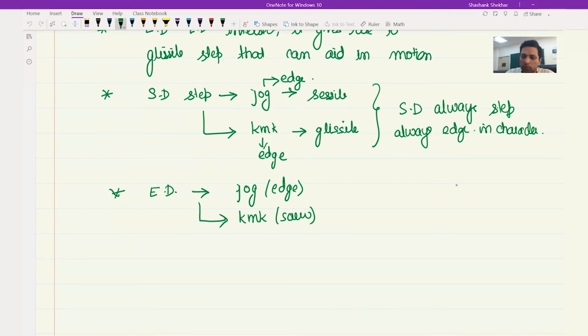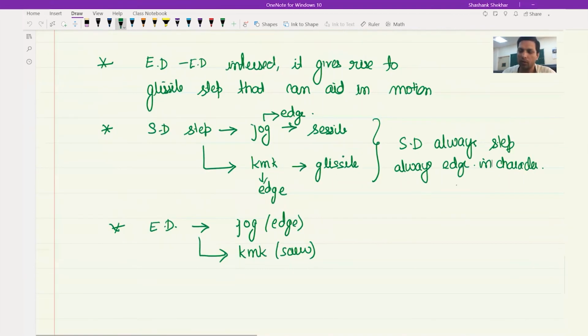So in this lecture, we have looked at step formation, the intersection of dislocations, which leads to step formation. And some of these steps can be sessile, which means they can pin the dislocation, and hence those pinned parts can, as we have seen earlier, lead to Frank-Read sources.